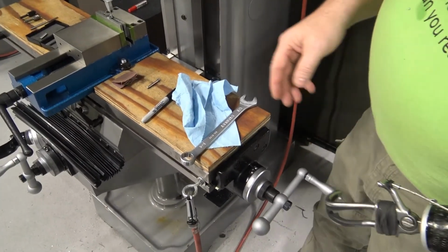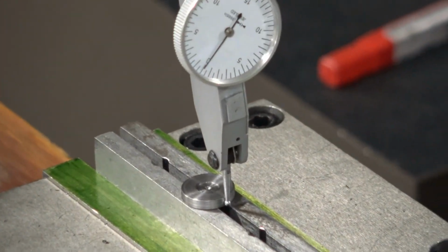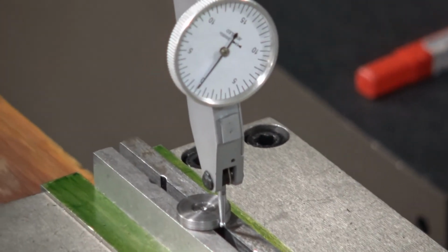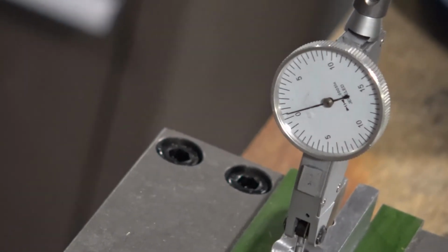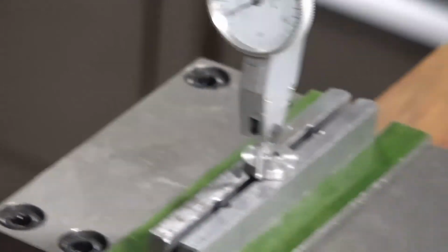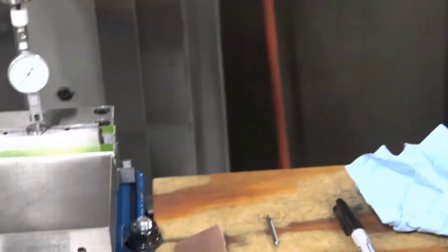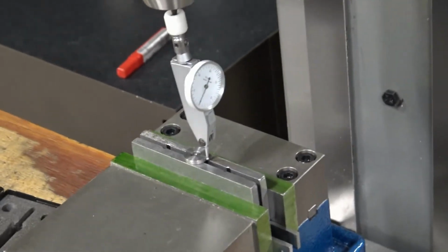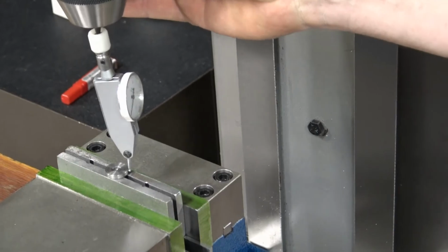Before I move off, I'm going to double check and make sure that I'm reading 0 all the way around that round stock. So I'm at 0. I was at 3 o'clock. I'm a couple tenths off on 6 o'clock. I'm around here to 9 o'clock. I'm a couple tenths off. If you want to fight over those couple of tenths, that's fine. It's just going to take you a little bit more time. And I'm going to just double check the backside, and I'm within a couple of tenths.